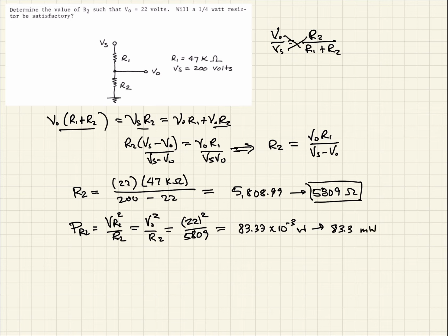In that case, that is less than 0.25, or a quarter watt. Therefore, a quarter watt rated resistor would work fine.